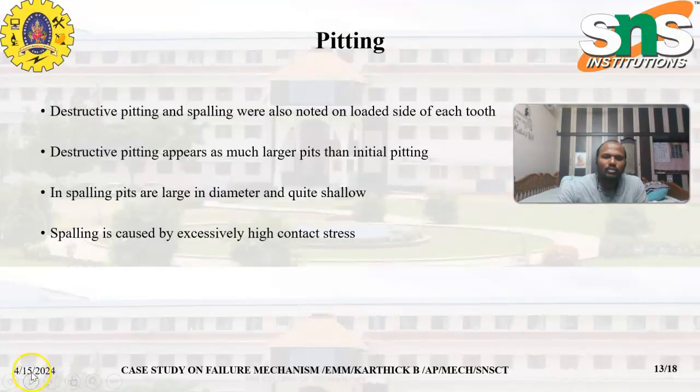Next is pitting. The destructive pitting and spalling were also noted at the loaded area of each tooth, and the destructive pitting area appears as much larger pits than initial pitting. In spalling, pits are large in diameter and quite shallow.